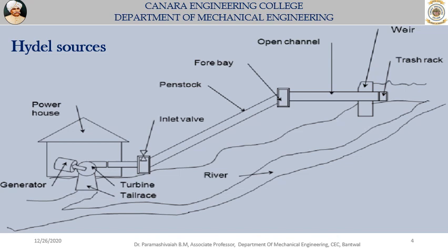See in detail, this schematic explains the arrangement for a hydropower plant. Here this is the flowing river. Before the water flows down the river, at the top itself, we construct a dam. Then we store the water in a reservoir, and that water is taken through an open channel, and this channel ends at a forebay. It is again a small reservoir, and from this the outlet is connected to the penstocks, which I told you about in the previous slide. Penstocks are the pipelines which carry water.